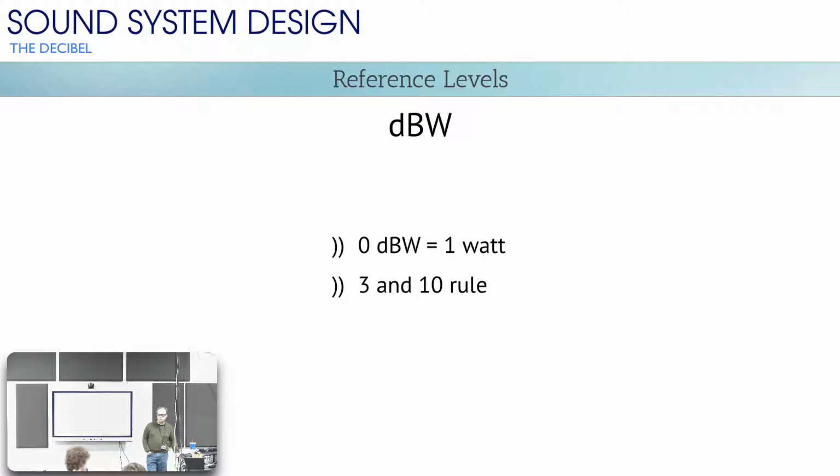Every once in a while you'll get into some larger numbers, but the absolute highest number I've ever really had to deal with on a power amplifier is 10,000 watts, and that's rare. So those are not enormous numbers. That's not like the difference between 1 and a trillion. Okay, so that shortcut of collapsing this wide range into dB is not as helpful when you're talking about really high power output levels for amplifiers, because it's not a huge range you're dealing with.